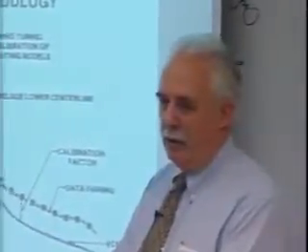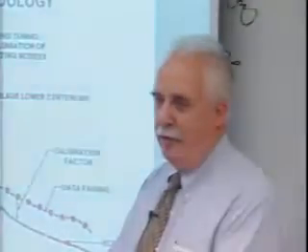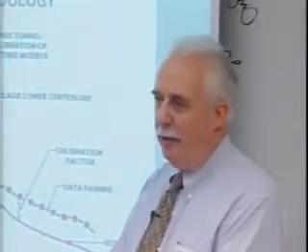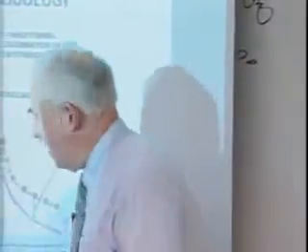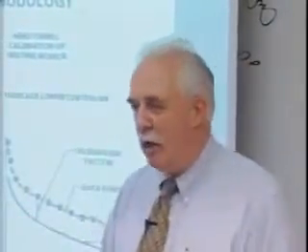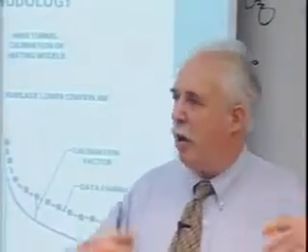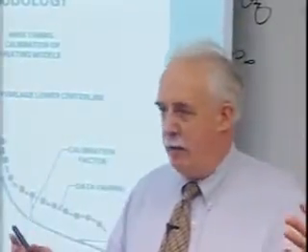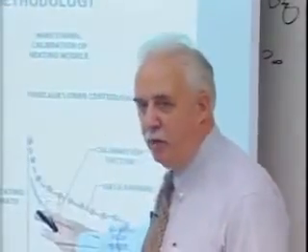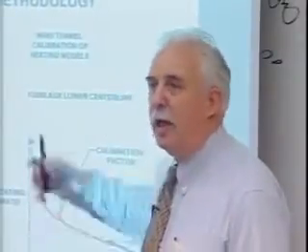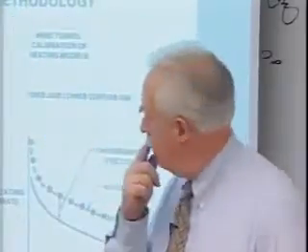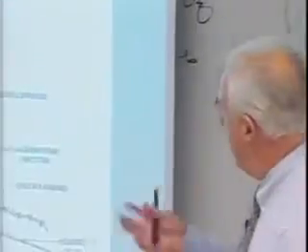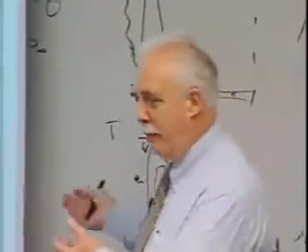A little factor in there, okay? But I assume, well, whatever I don't know in the wind tunnel, I don't know in flight too, okay? But I take this analysis, which can include the chemistry, all the nice things that go on in flight. So I calibrate it to wind tunnel, which is basically an empirical flow field now, and I take that to flight. Works pretty well, really does, okay? Better than my normal shock Reynolds number that I gave to the trajectory guys.